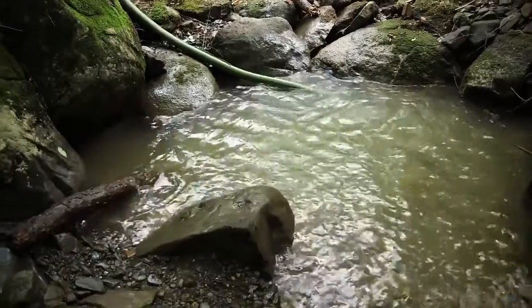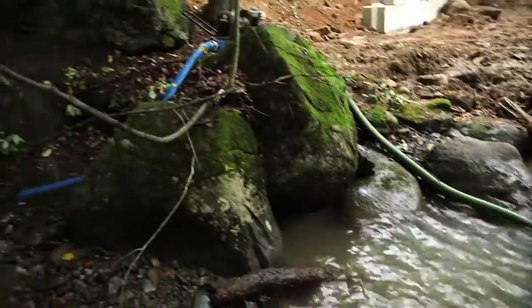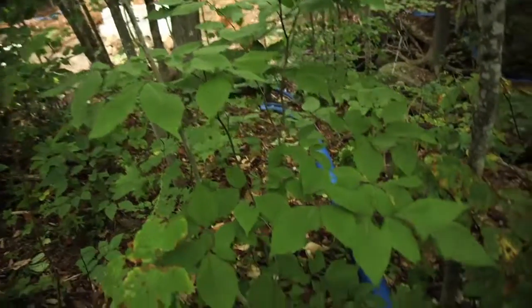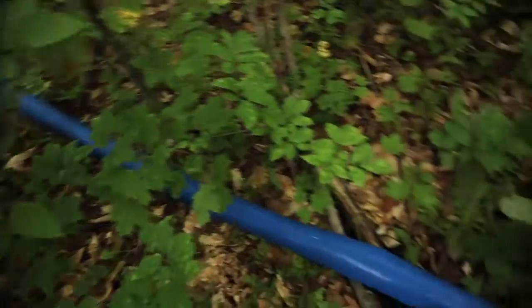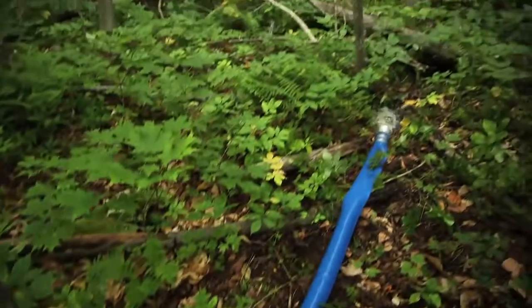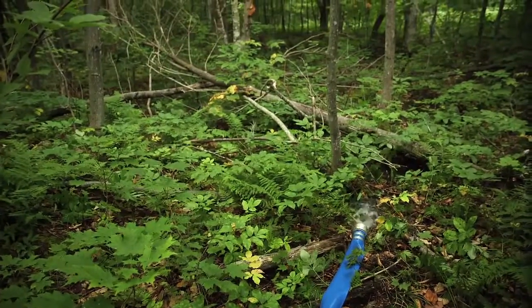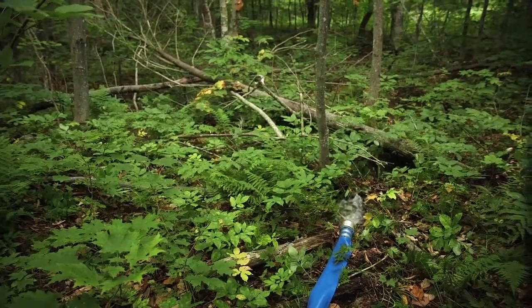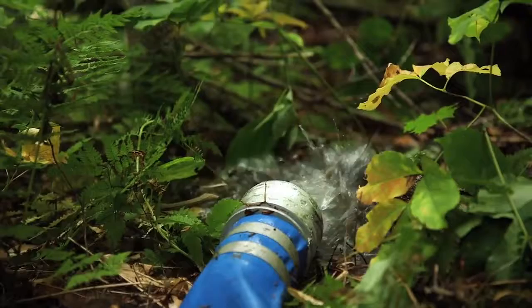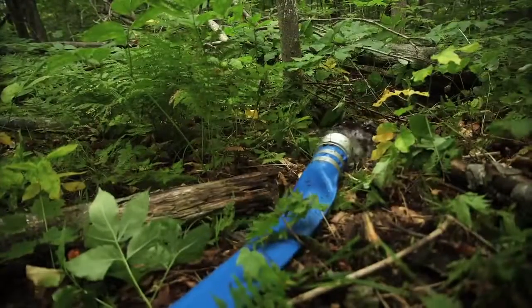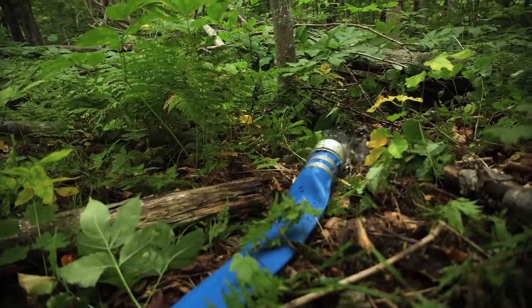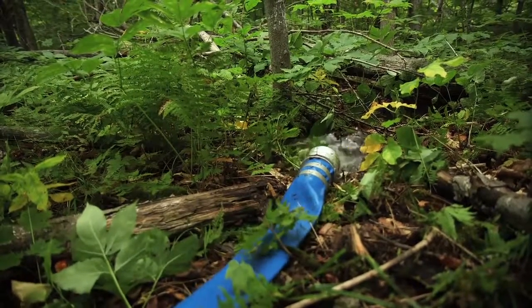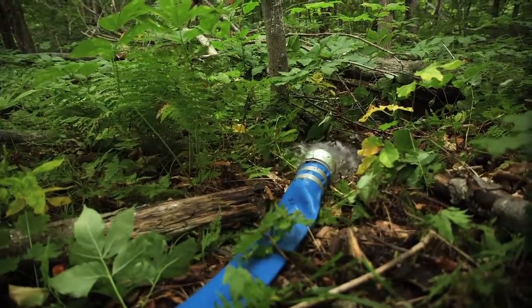A downstream sump was used to collect any groundwater encountered at the disturbed construction site. Dirty water collected in this sump was pumped into the woods far enough from the stream that the sediments in the disturbed groundwater were filtered out before returning to the stream. For sites where the groundwater flow is higher, a temporary sediment basin may have to be constructed somewhere off-site for the disturbed groundwater to flow through before entering back into the stream below the site.